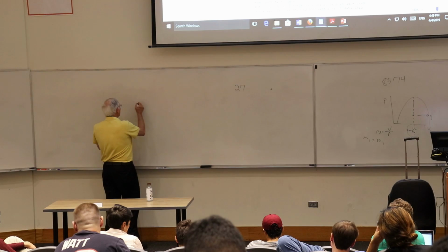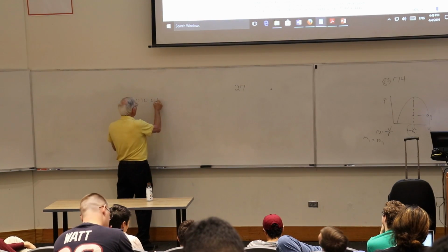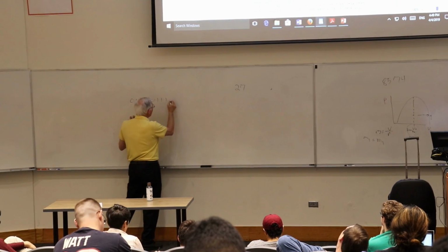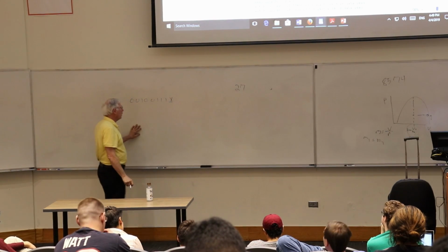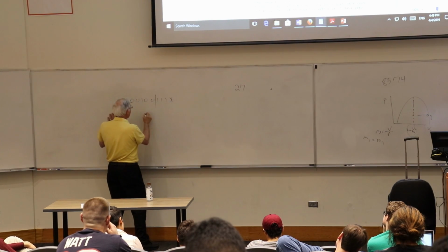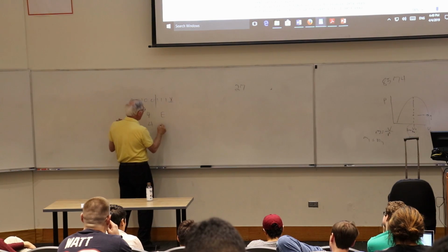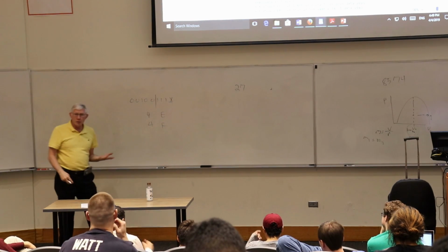So here we have 27. That would normally look like 00100111. But now we're going to append our read-write bit here, and so now all of a sudden we have 4E or 4F, depending on whether we're writing or reading.